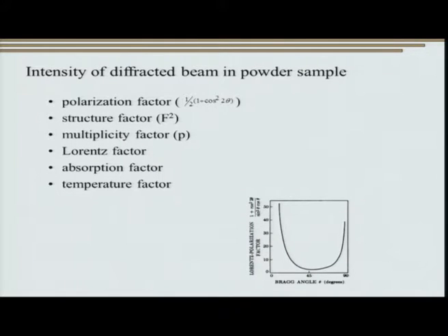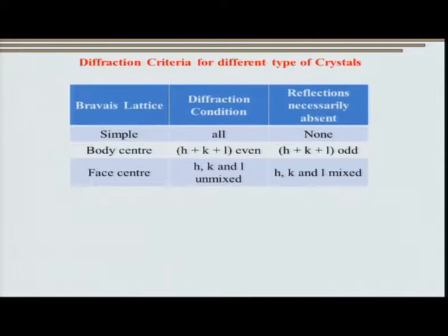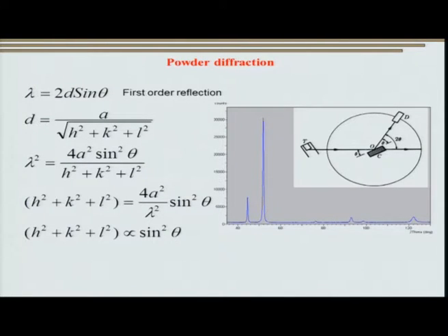Having said that, you must have noticed the intensity of the peaks which I had shown in the earlier slide. Herein, after gaining knowledge about the kind of reflections and the Bravais lattice, I hope you can make a guess that this material showing two peaks very close separated by a third peak, and again two peaks close separated by another peak, corresponds to an FCC crystal structure with reflections at 3, 4, 8, 11, 12, 16 and corresponding to 111, 200, 220, 113 and so on.